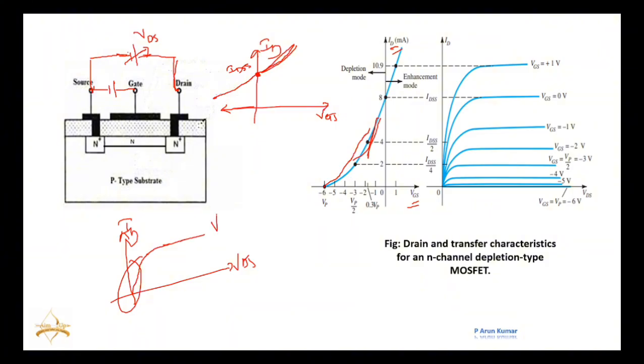Let us say VGS equals 3 volts, that is positive voltage 3 volts. If I give VGS equals 4 volts, the effective channel will increase, right? In that case, the current will again increase. Then the graph will look like this. This is when VGS equals 4 volts. If I decrease this VGS, then the effective channel will decrease, and the current will decrease. So this graph will be shifted downwards like this. So at VGS equals 0, we'll get the graph like this one.